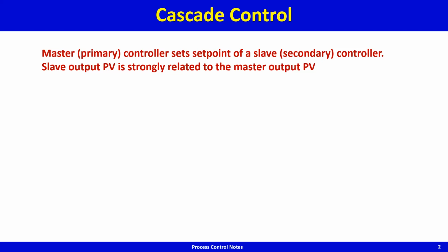The idea is that the slave process variable is strongly related to the master output process variable, and thus by controlling the slave process variable you get better, or tighter, control of the master output process variable.